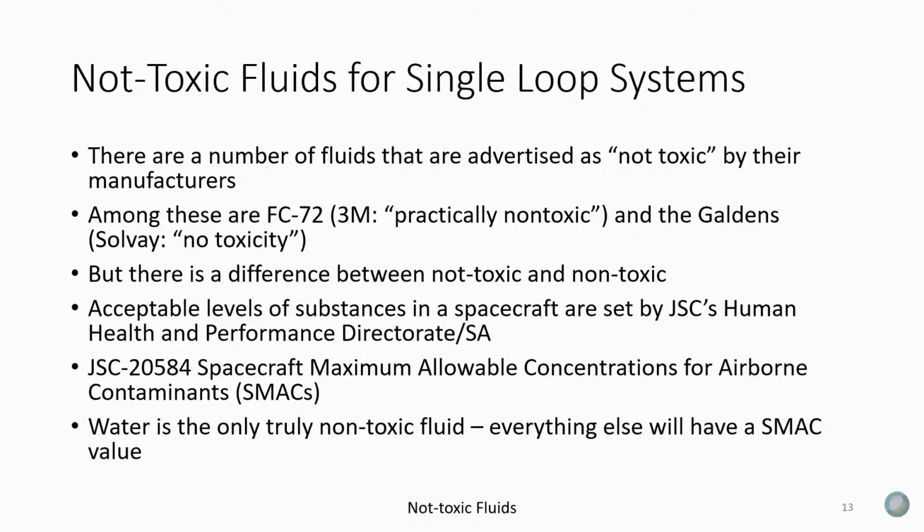And Kayla, I saw you flash across a question. Does the saturation pressure of the fluid affect the performance? Not particularly, but what the saturation pressure does is it tells you what pressure you have to run your accumulators at if you're a single phase system, and that changes the design of your system. But it doesn't really play in terms of the performance, but it does play in terms of how thick your tube walls and how thick your heat exchanger walls have to be.